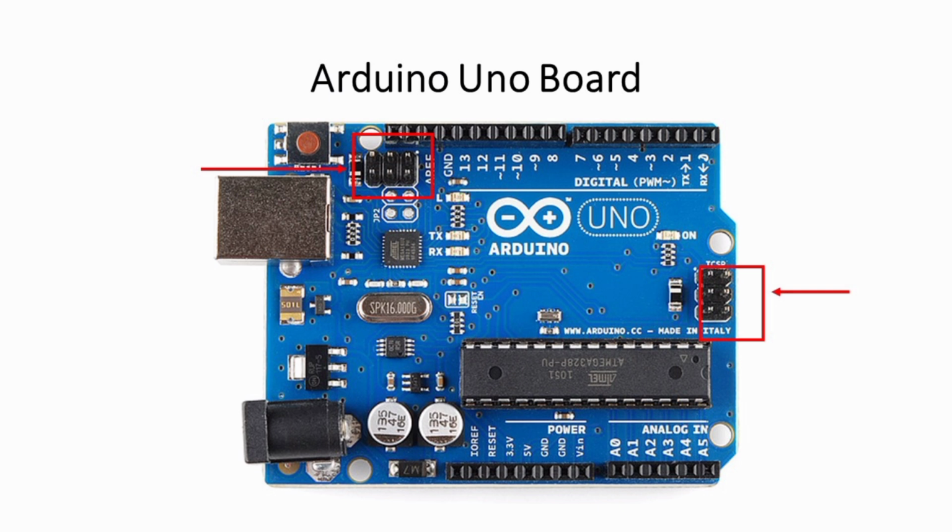There are 6 dedicated pins for ICSP. It stands for In-Circuit Serial Programming. It is a special programming method to program the firmware. This is needed because the firmware, also known as the bootloader, cannot reprogram itself. In Arduino Uno, there are two ICSP ports for the two microcontrollers. These are called ICSP headers, each consisting of 6 dedicated pins.